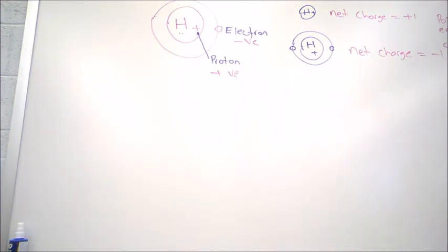If more current is flowing through the conductor than it is rated for, then the conductor will heat up and eventually it's going to melt. And when it melts, it breaks the path for current to flow. That's why you normally see fuses with glass around them. If you've seen those that are clear, there's a thin wire inside. When that melts, the path for current to flow is broken. So in other words, current is not going to flow through the circuit.